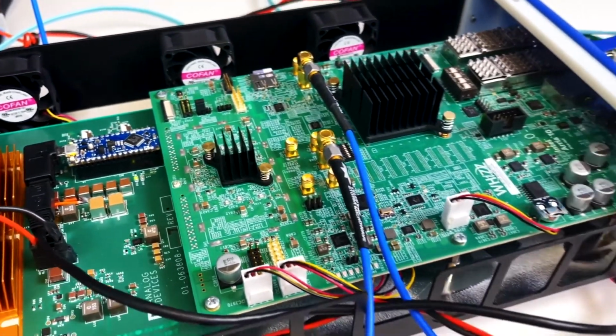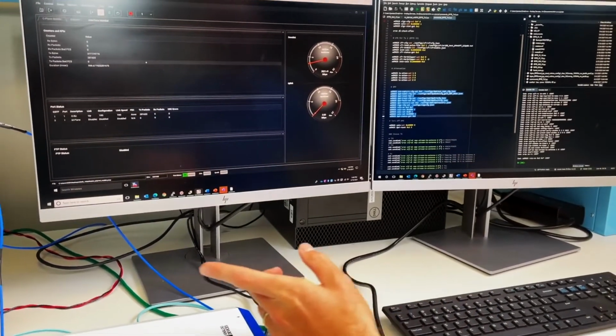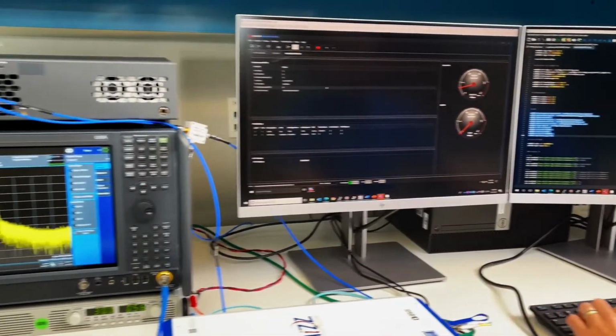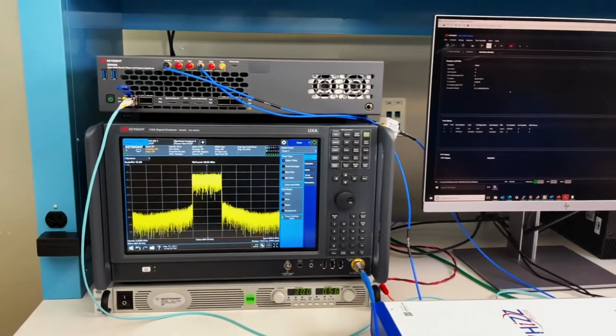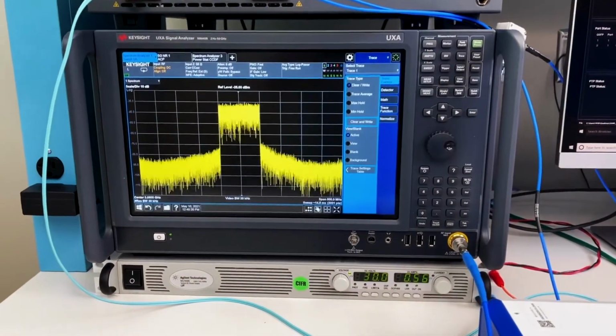power per transmit channel and includes the ADRF5515, a 20 watt dual channel receiver front end with integrated LNA and high power switches. To test the O-RAN compliance and 3GPP capabilities of our O-RU, the Keysight O-DU Emulator and Open-RAN Studio software is used together with Keysight Signal Analyzer and sources.